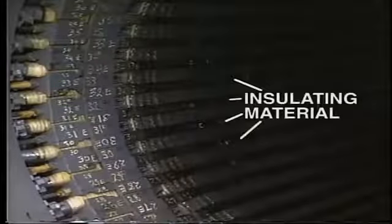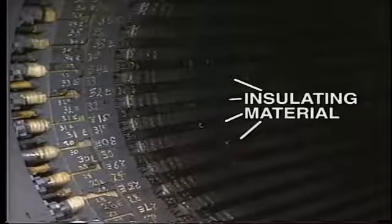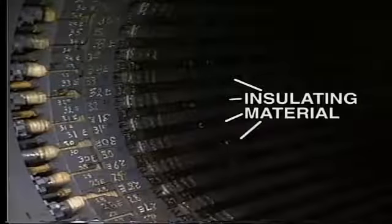Once the stator bars are fitted into the core slots, they are joined at the ends to form continuous coils or windings. These end connections are referred to as end turns. The conductors are securely held in the slots by wedges of insulating material. This is extremely important, as the windings are subject to quite heavy mechanical forces during operation.